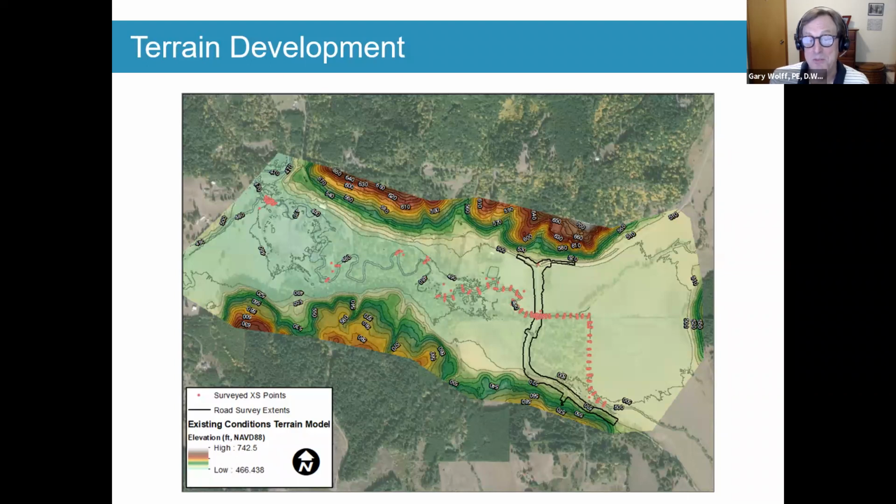Another common two-dimensional model that you may be hearing a lot about these days is the Army Corps HEC-RAS program, which now also has two-dimensional modeling. It is somewhat limited, however, because they don't have the bridge routines now built into HEC-RAS. So that, and for other reasons I won't go into right now, the Federal Highways right now is really promoting SRH-2D for hydraulic design of bridges.